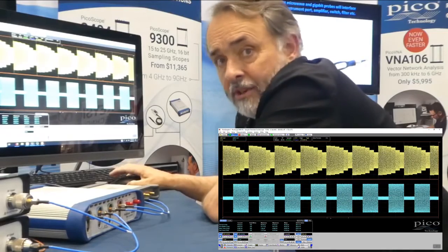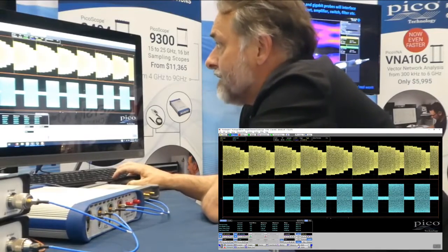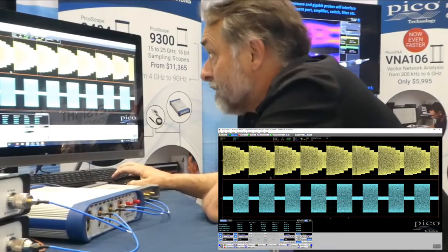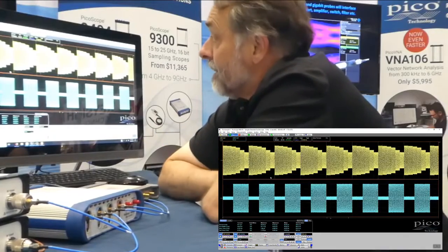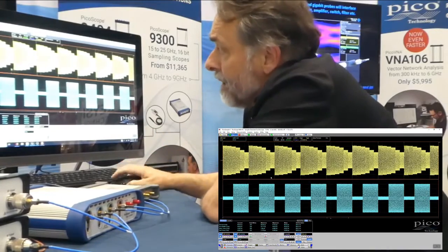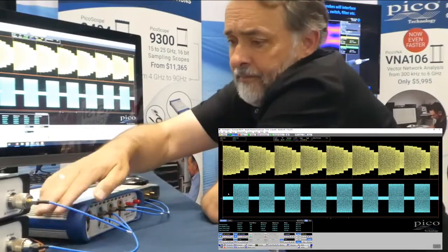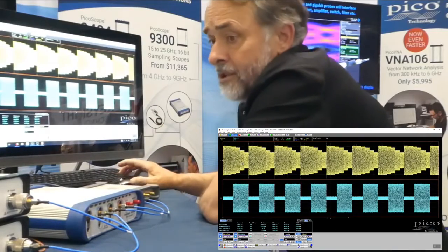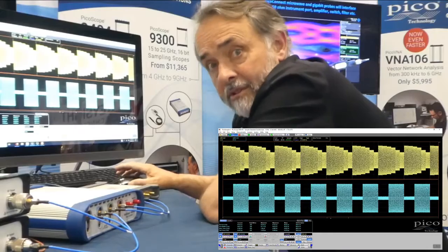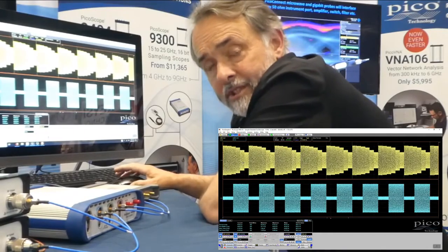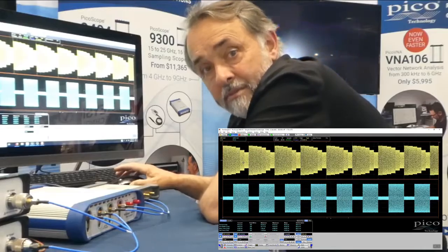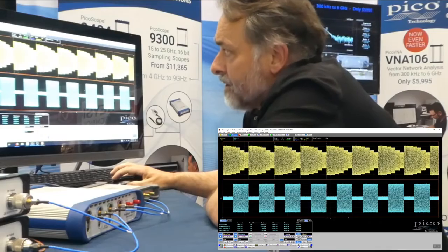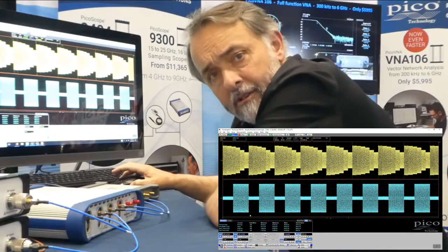The AS108 is generating that pattern. The pattern duration is about 5 milliseconds per division. Yeah, just over 5 milliseconds that pattern at the moment. On the bottom here, into channel 2, I'm using the second AS108. The two synthesizers have been synchronized together. That's one of the important facilities on the AS108. We can synchronize multiple units. So down here I'm generating a little burst of 2 gigahertz carrier.